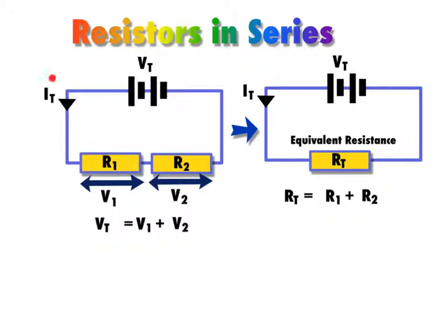And then we can take that total current back into the original circuit and find a voltage by multiplying current by resistance, and find another voltage by multiplying current by that resistance. So there's a lot you can do with a series circuit, and it'll become more obvious when we get values into these and look at them later.